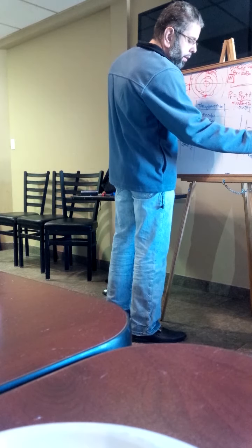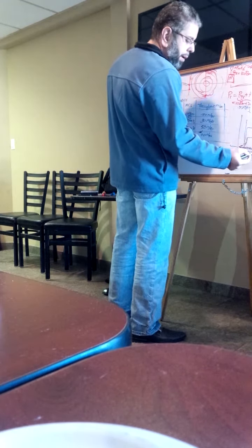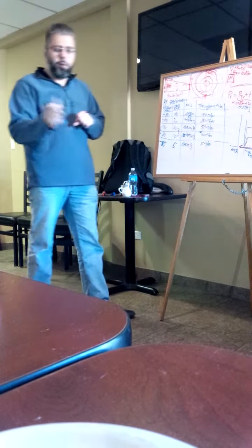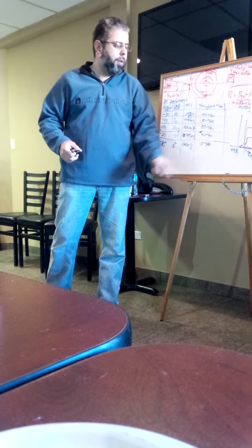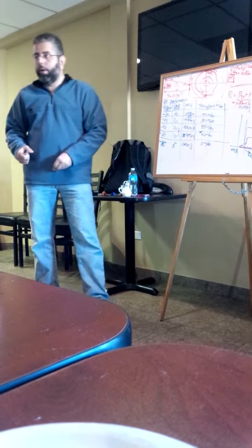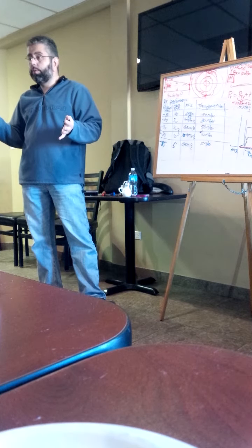My interference. So now my carrier to interference plus noise ratio, the interference is way above the noise. And I want you to do this exercise later to convince yourself. If you were to add minus 70 dBm and minus 95 dBm, I'm going to tell you the number is going to be minus 70 dBm.